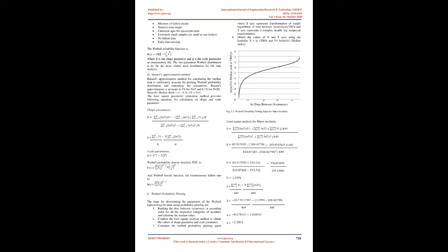These products are subsequently subjected to various treatment and separation processes, such as extraction, hydrotreating, and sweetening, in order to produce finished products. Whereas the simplest refineries are usually limited to atmospheric and vacuum distillation, integrated refineries incorporate fractionation, conversion, treatment, and blending with lubricant, heavy fuels and asphalt manufacturing. They may also include petrochemical processing.